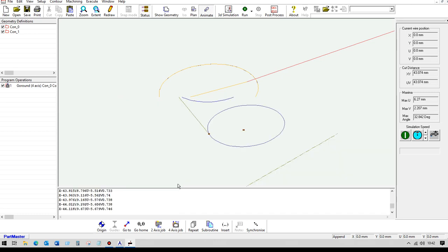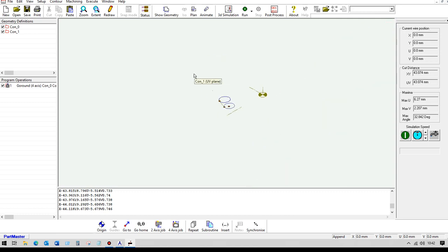So you would need to do that for each one of those contours, each one of those cavities, but the effect would be that the program will start at the datum, rapid to the first contour, cut, and then proceed to the next position, thread the wire, cut round, stop, cut the wire, rapid across to the next position, and so on and so on.